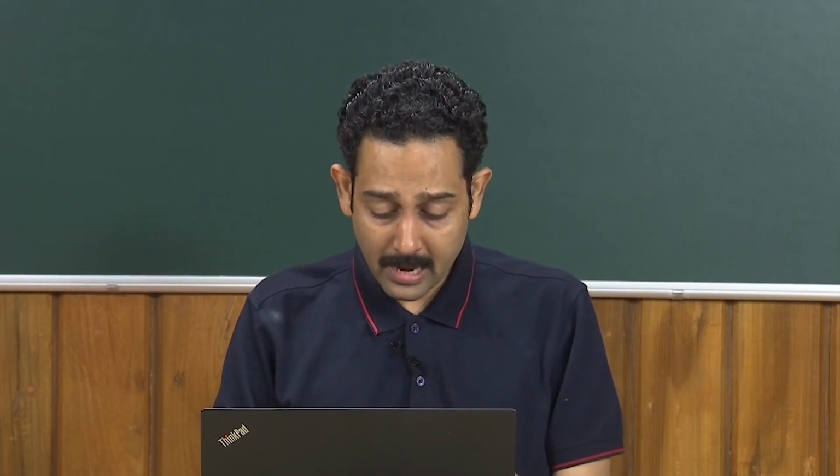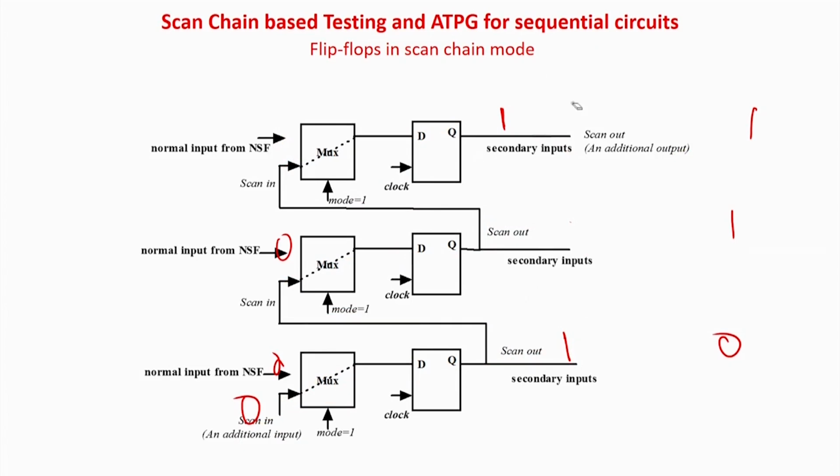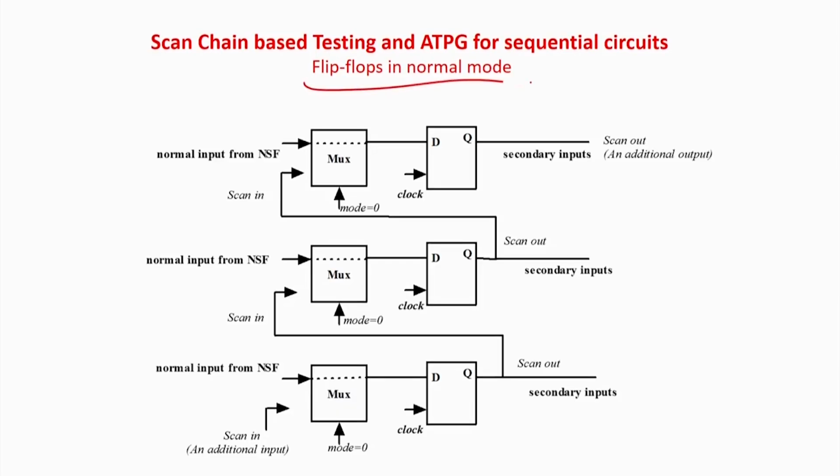Because as you can see, it is a simple scan chain or simple register, so the delay is very less, because one flip flop will be connected to the other and so forth. So from the digital fundamentals you can apply very high clock speed to transfer the data, because delay is almost negligible, as it is one flop to other and so forth. There is no combinational circuit in between. So the scan data can be fed very fast. And now when the scan job is done, basically you can see the flip flops are in original mode.